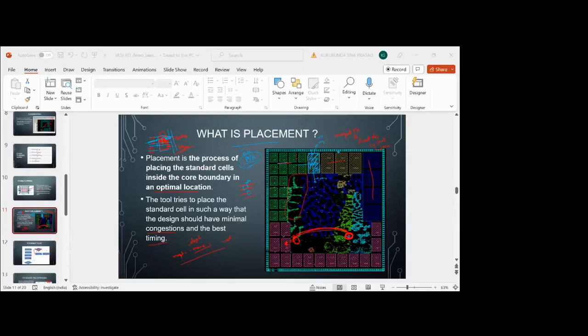I told two: one is the slack, and the other is the more violating paths, because if you fix this, all 100 will be fixed, right? Yes. So there the engineer is involved. That is the power of analysis. If you do analysis, then you can fix in one iteration. Otherwise, people start fixing only one, and for 100 they will use 100 different commands. If you find the common point or valid point, then you can fix in a single go.